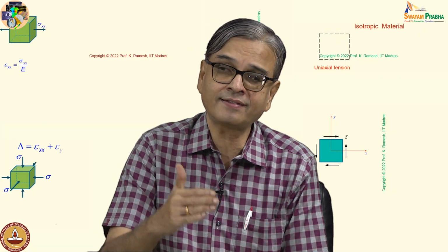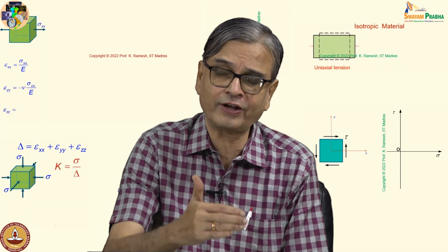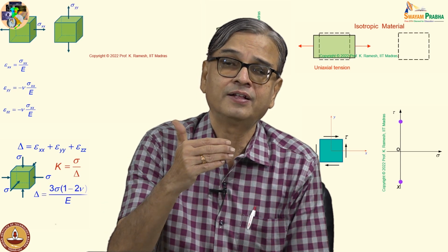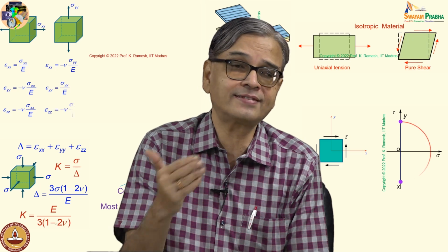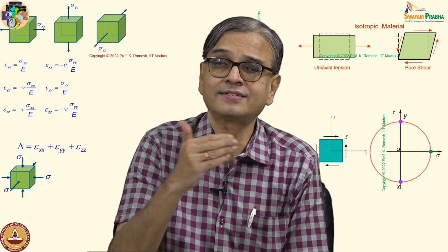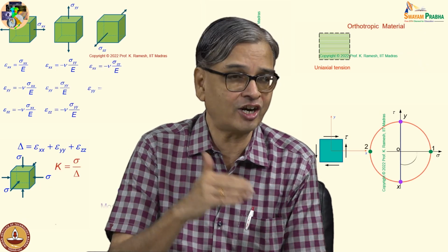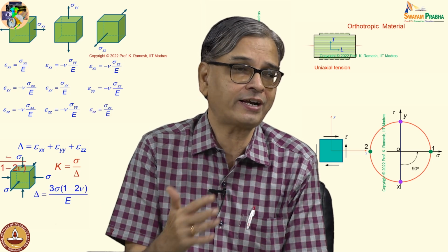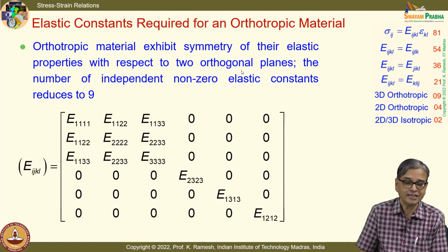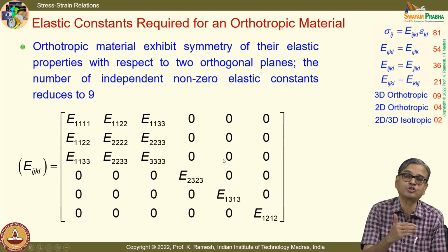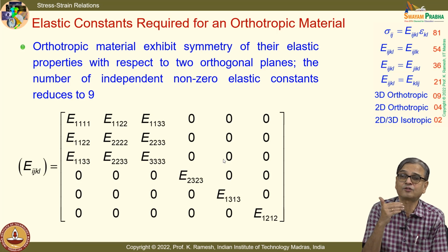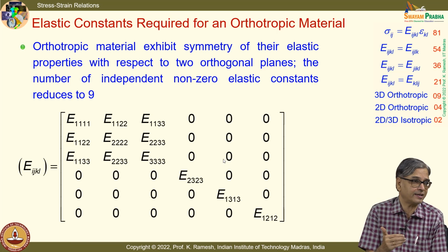So you bring in the symmetry condition and go further, because elasticity is a tensor of rank 4. When I look at symmetry, on the symmetric axis the elastic constants cannot change. You will have some contradictions, and those contradictions will say that these constants should go to 0. That is how you get the zeros here. You extend this argument, and you can also show that an isotropic material will have only 2 elastic constants.